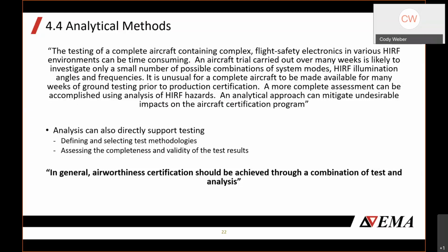The testing of a complete aircraft containing complex flight safety electronics in various HIRF environments can be time-consuming. An aircraft trial carried out over many weeks is likely to investigate only a small number of possible combinations of system modes, HIRF illumination angles, and frequencies. It is unusual for a complete aircraft to be made available for many weeks of ground testing prior to production certification. A more complete assessment can be accomplished using analysis of HIRF hazards. An analytical approach can mitigate undesirable impacts on the aircraft certification program. It can also be used to help define and select test methodologies, and then also assess completeness and validity of the test results.